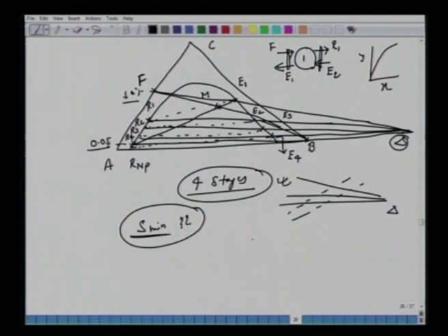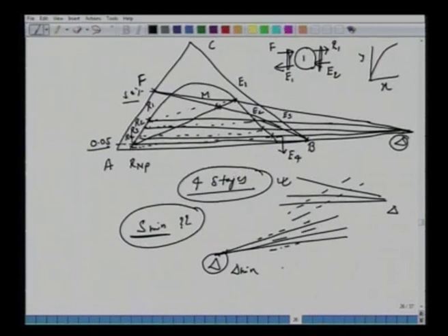Had the delta point been on the left hand side, so that we have the tie line like this and also the operating line connecting to this left hand side delta, now there is a risk of this operating line coinciding with this equilibrium curve. In this case, yes, we can have delta min, then take 1.5 or 1.2 times to make it delta operating. All right.